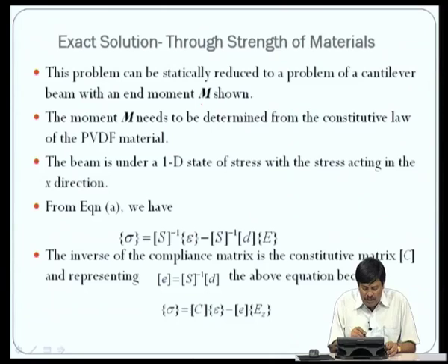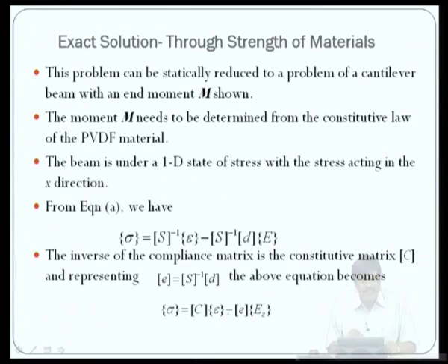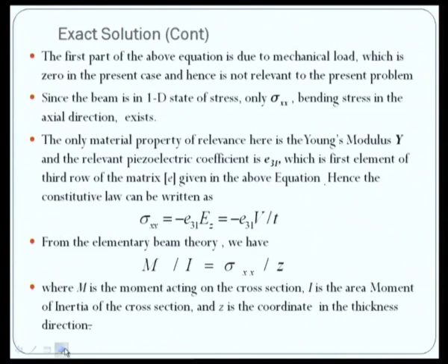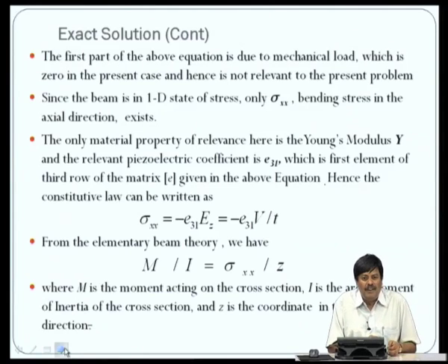From the constitutive law, that is the actuator law, we have sigma equal to S inverse times epsilon minus S inverse d into E. So, we can write the constitutive law in this form, where e is the piezoelectric coefficient which we have derived earlier. The first part of the above is due to the mechanical part, which is 0 in the present case, because there is no mechanical loading applied.